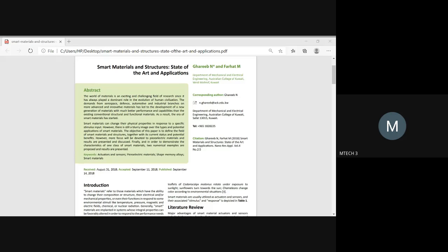For all these three, it is mandatory that polarization has to be done, whether it is pyroelectric or piezoelectric. Electrostatic polarization has to be done. If it is magnetostrictive, then it is always subject to the amount of magnetic field applied. These are the things you have to keep in mind. Similarly, for the other classes of materials, you have the stimuli to which they change. Electroluminescent materials change with respect to the electrical field. Photoluminescent materials depend upon the incident light. Similarly, you can go on for the others.